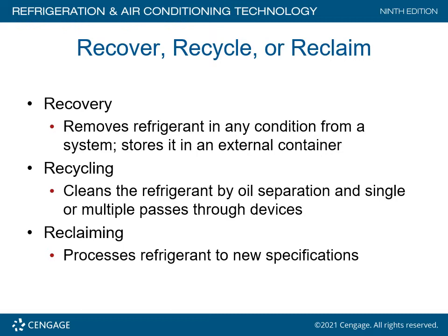There's machinery available to do this on the job site. Typically, as a service tech, you will not be involved with this process because the equipment is quite expensive and requires a lot of filtration in order to achieve this recycling method. Reclaiming processes refrigerant to new specifications, which I believe is ARI 700.